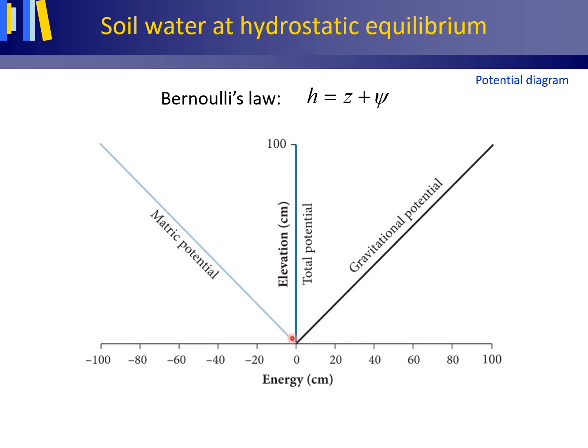Thus, by defining the pressure head at the water table as 0, same as for groundwater, water pressures in the unsaturated zone are negative, that is, less than the existing air pressure. When we move 10 centimeter above the water table, the elevation head equals 10 centimeter and the pressure head equals minus 10 centimeter.